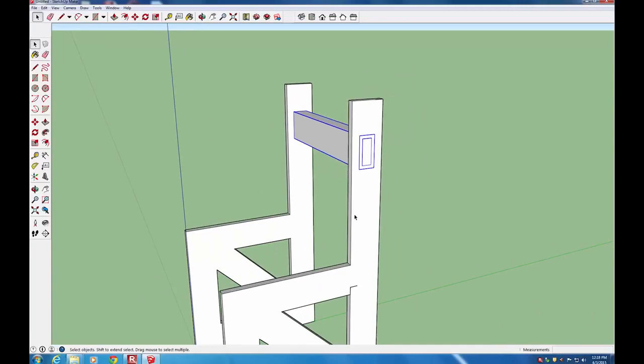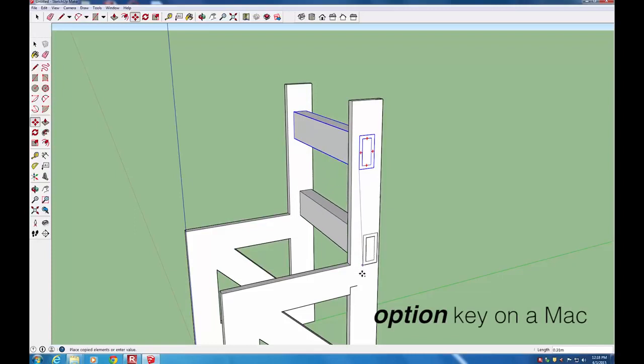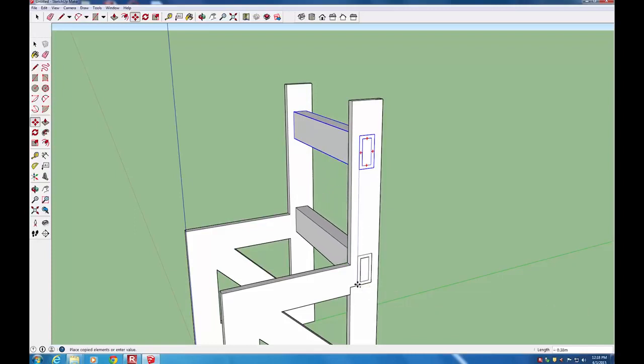So next we're going to copy this rectangular tube down the model into a couple of places. So just like we did before with the chair, go over and click the Move tool. And in this case, we've got to be careful with what we're selecting when we go to move. So I want to move this bottom left corner of the rectangle to this point down here. So I'm going to click on the bottom left corner of the rectangular tube, click Control, and then start moving down and snap it to the endpoint that I already created down here.